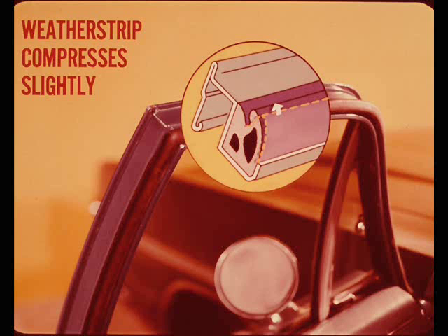You see, when a door is properly fitted, the weather strip compresses slightly as the door closes. This allows the strip to make firm, even contact all around the door opening so it can maintain a good seal without being flattened or crushed.